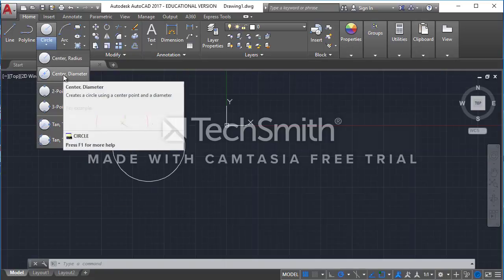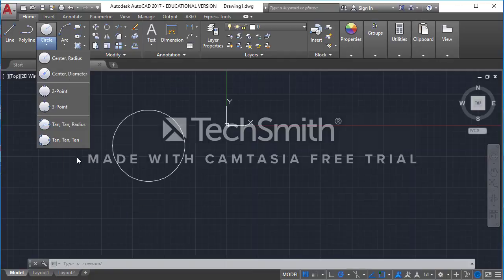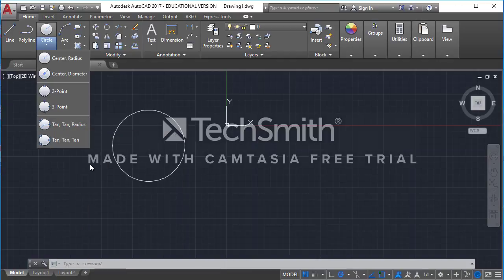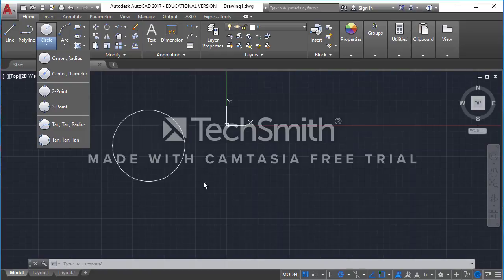So if, for example, I don't want to input a radius and I want to instead input a diameter, I can do that. It just depends on how you want to work. There are several other versions. I'm not going to talk about these as I usually don't use them, but depending on how you use AutoCAD, you may have a reason for needing to input a tangent, another tangent, and then a radius to get some more complex shapes. But that definitely falls into the category of more advanced AutoCAD techniques.